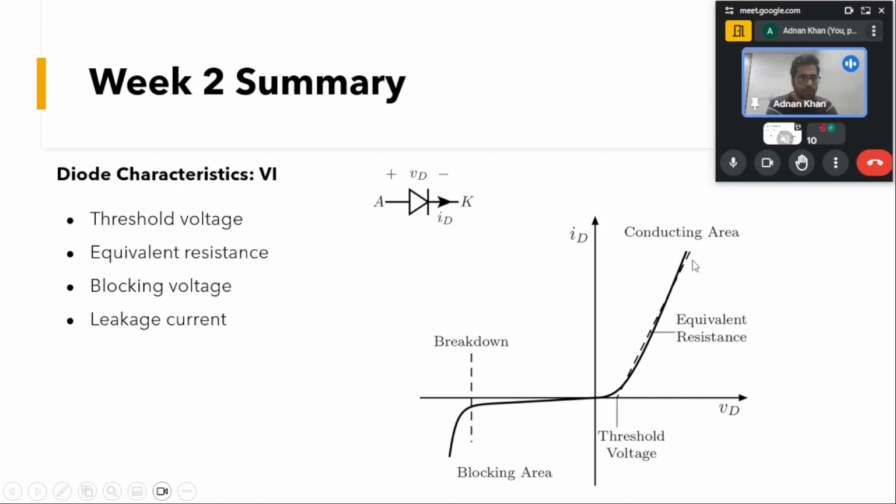So you can see, we should operate our devices in the region where they should be able to withstand this amount of blocking voltage in our topology or any circuitry. And if you see the data sheet of any device, there is a limit given for the amount of current that a device will be able to conduct. So we should operate our devices between those limits.